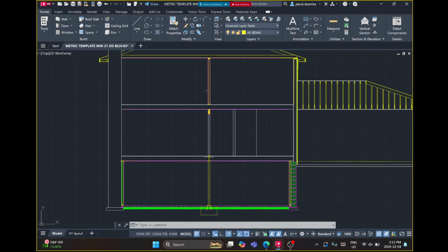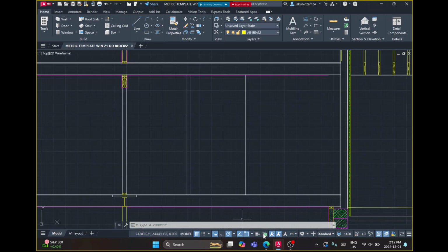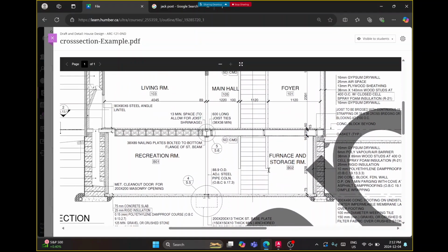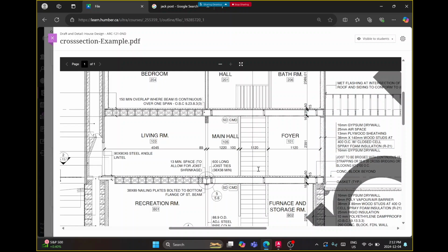So we have our walls in the middle. Now we can detail our stair. This should be relatively simple. So we have these 3 lines. We know that this is some kind of a wall. Somewhere here we have a railing. And we should have from our detail drawing the riser height. So we simply strike a line and just start offsetting on it to show our riser heights.